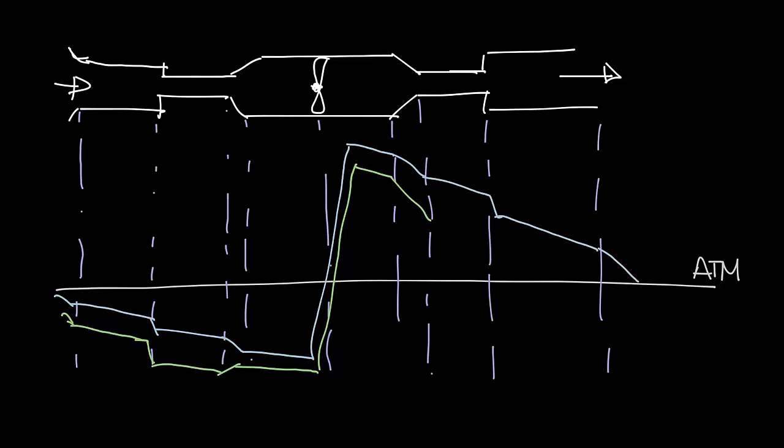Now the velocity increases, so the static pressure will be reduced. Then follows the ductwork, and now we have an abrupt change. The velocity decreases, the static pressure will increase, follows the ductwork, and then out into the space.